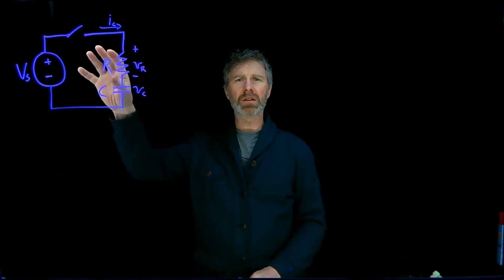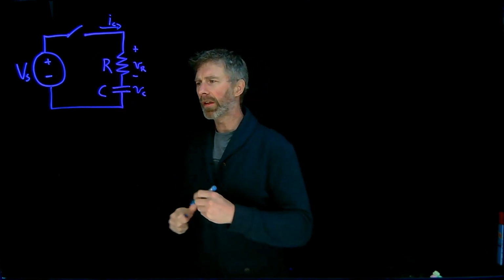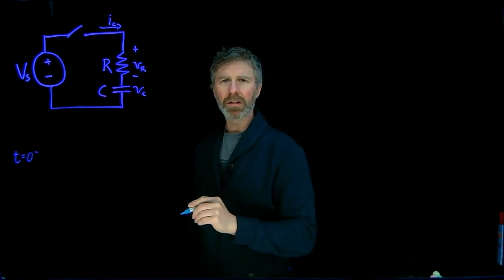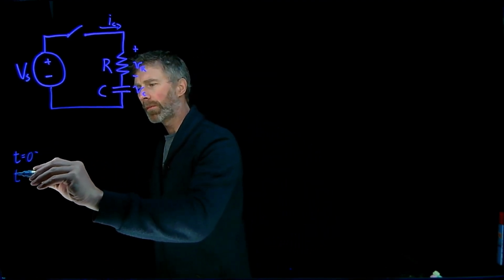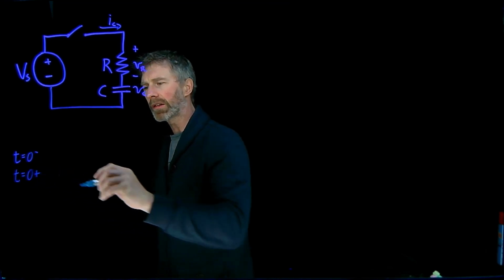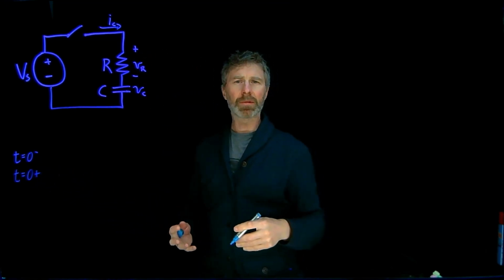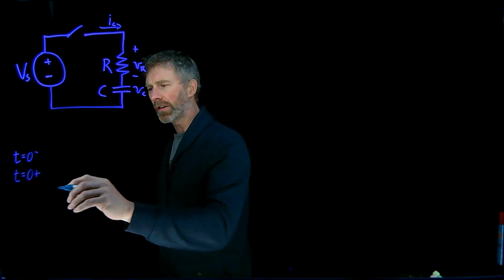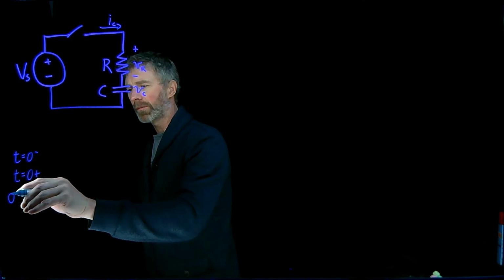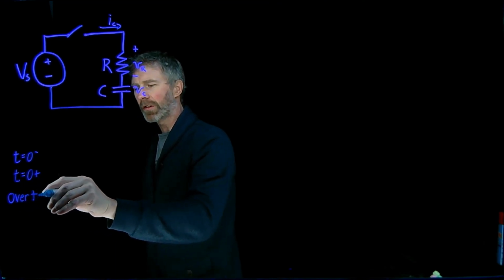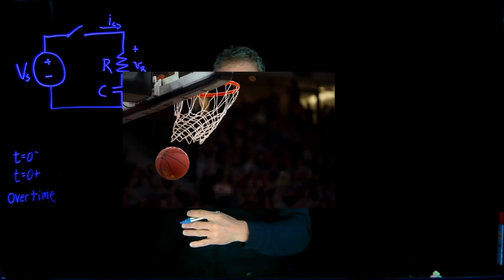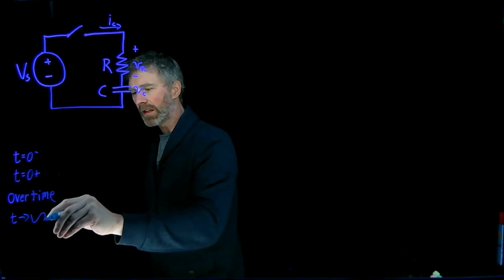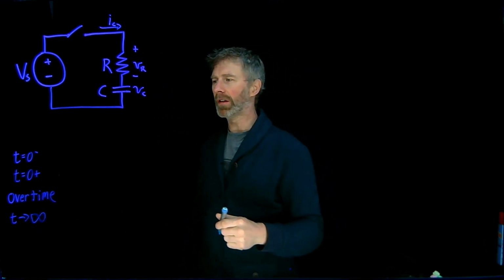One is the instant before the switch closes, and we're going to call that t equals 0 minus. One, the instant immediately after the switch closes. We'll call that t equals 0 plus. We'll also look at what's happening between the time that the switch closes and the time when the capacitor is fully charged. And then finally, as t approaches infinity, we'll see what infinity means.